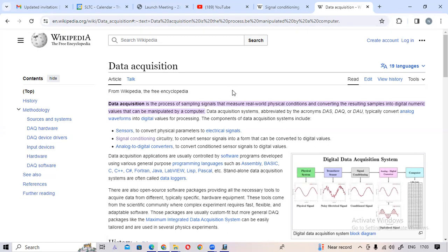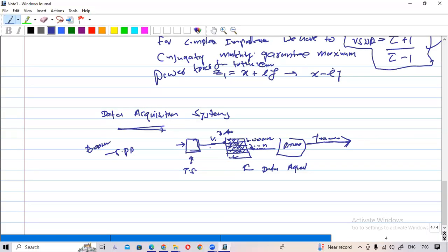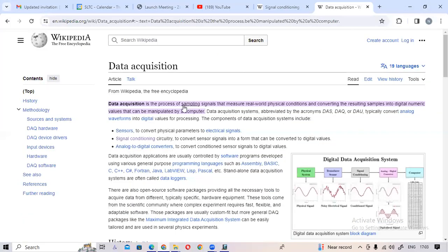So simply, here we actually got analog values. Here we have an analog signal. That analog signal we have to convert into a digital signal before storing it in the RAM. That is why we need sampling and analog to digital conversion, because real-world data is always analog. In the process of sampling, we have to get some samples.